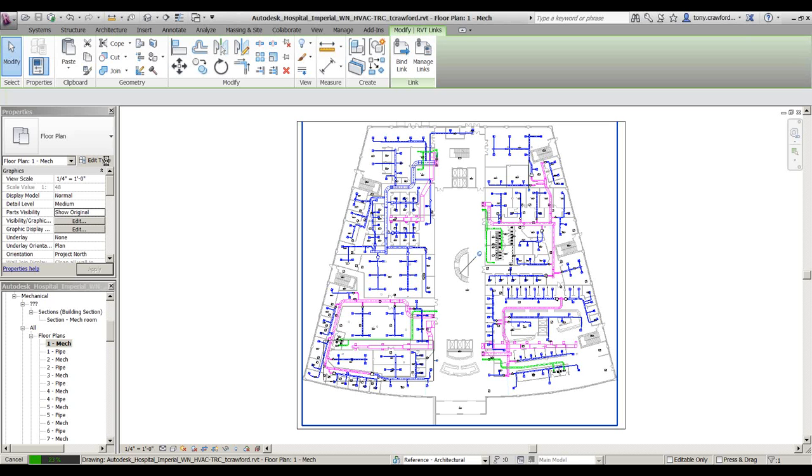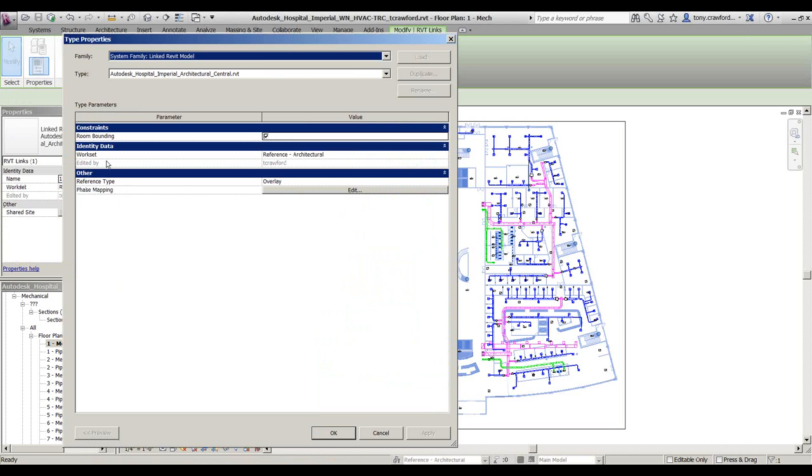You don't need 3D objects for everything in your model. You can use 2D line work to represent a 3D thing. Exactly. And it will show up in 3D. And I would encourage you to do 3D, but a very, very simple one. Because sometimes, say if I'm doing a low voltage design, you wouldn't think I'd care about furniture in 3D, but I've had a project with a tiered classroom, and I needed to see how tall the chairs were, where the ceilings were at, to get a sight line for the projector to the screen.